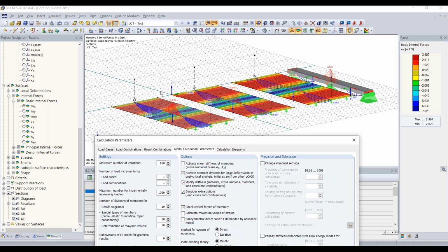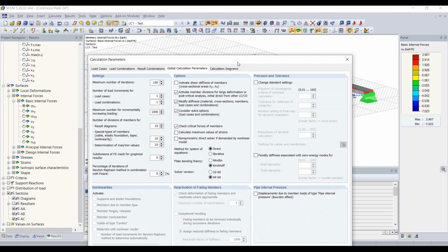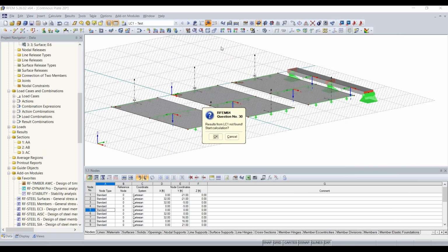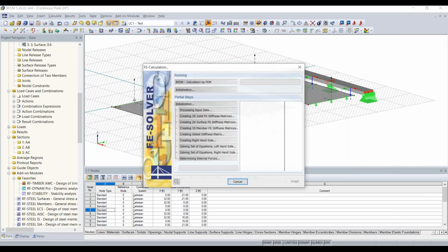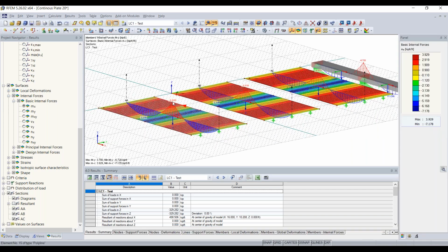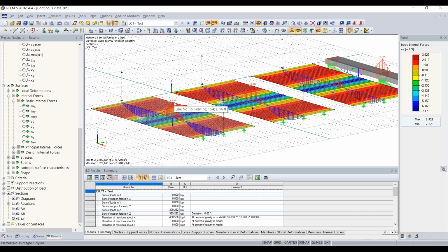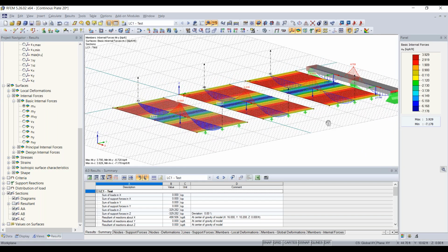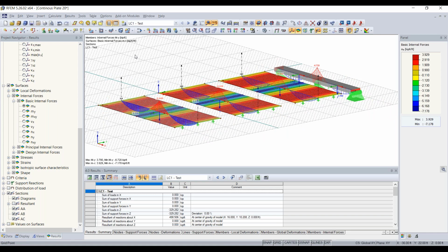If we switch to that right now, you can hopefully see these results. About 6.592, we'll just keep an eye on this one, 6.594. If we change this and click OK, it's going to ask us to recalculate. If we run this calculation again, we should see that our bending moments will increase from the decreased deformation. So yep, 6.6. It was about 6.59. So not much change in results, but still increased accuracy with the Reissner-Mindlin theory.